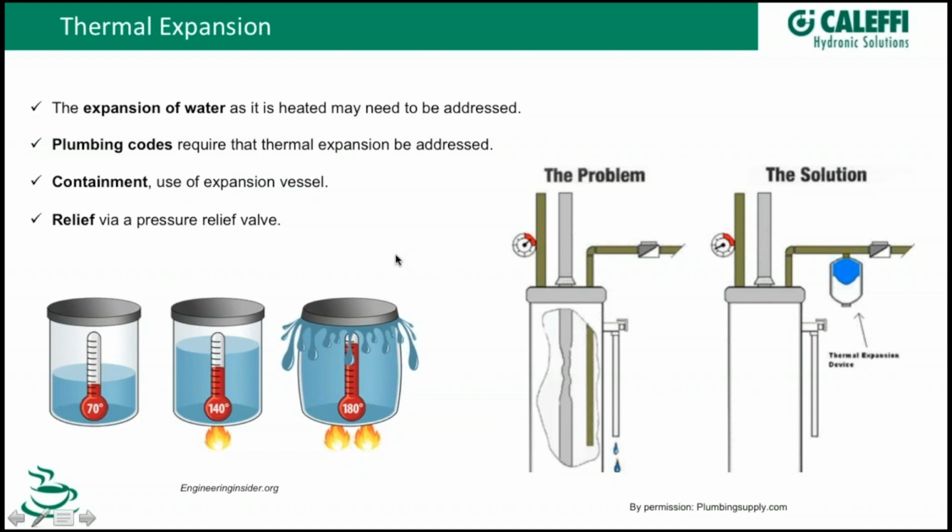One of the things that will do that for you, which isn't really what it's designed to do, is the pressure relief valve here. Typically on a residential water heater, this valve is going to be 150 PSI and 210 degrees where it starts to relieve. What'll happen is if you get up to that 150 PSI, it'll start to drip or seep a little bit. And if that pressure keeps going up, eventually this valve is going to open up. There's just basically a spring in here. That valve is going to open up and discharge a big stream of water, and it's going to make a mess somewhere unless you have that piped into a drain.